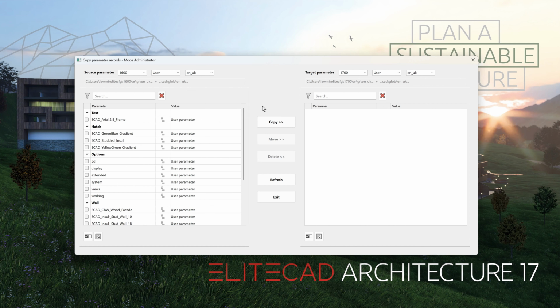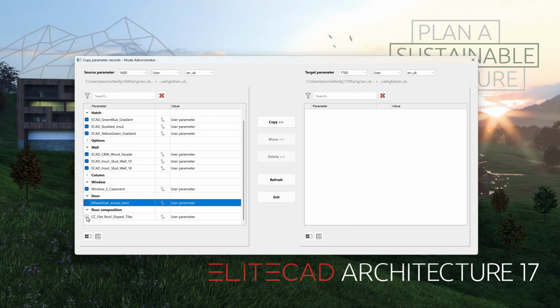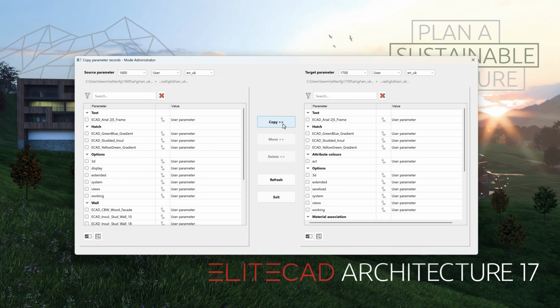All user parameters from the selected version are now displayed on the left-hand side. We can now either transfer them all at once to the new version or, as in my case, select a few specific parameters. Now you just click on Copy and the parameters have already been adopted in version 17.